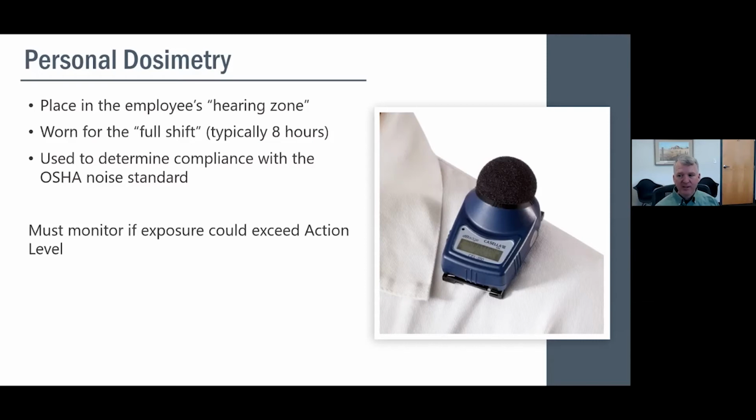One other little tidbit: if you have employees, especially maintenance, that have walkie-talkies or two-way radios, sometimes keying the microphone has interfered with our noise results. We've gotten some really quirky results, and we determined that was what was causing it.